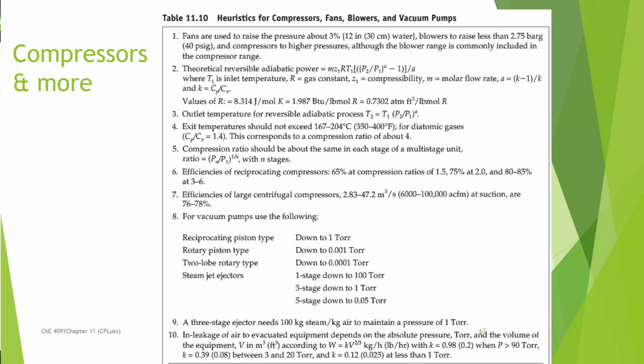And a blower can increase the pressure a little bit higher. But if you need something even higher than that, then you're going to want to use a compressor. Okay, now again, blowers and compressors frequently get kind of muddled in the literature when you're looking for data on those. There are all sorts of guidelines here about what kinds of expectations you can have for inlet and outlet. And remember that generally we don't want to compress to more than about 3 times the feed pressure in any one stage.